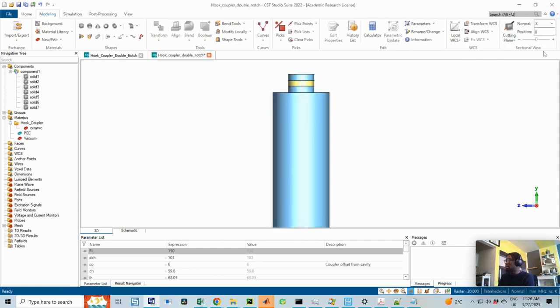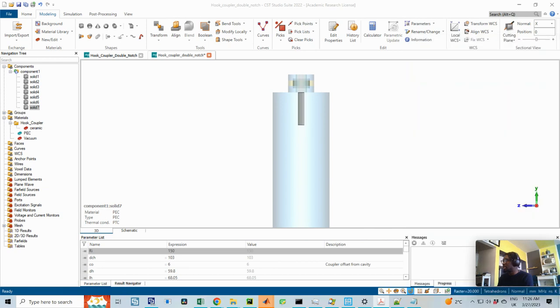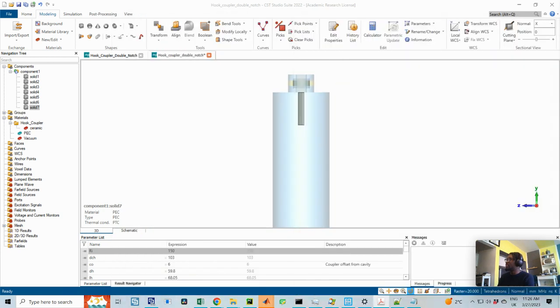Okay, then the next one I want to model is this cap. So I think I give it a thickness of 5 millimeters. That's just random, and I don't think it's part of the variables here. The thickness of this cap is 5 millimeters, and it's also a cylinder. So the y min would have to be the current minimum, and then just offset upward by 5 millimeters.